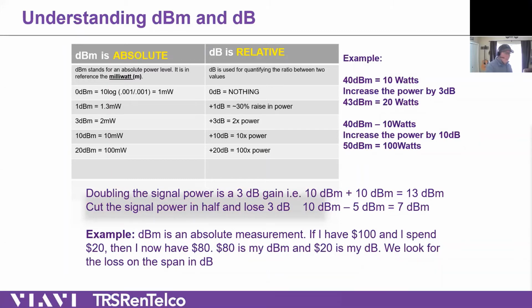And that number is good because obviously you need to know what that number is at the end, but you're not going to know how well your network affected that number. Hence the dB, or the relative value, right? So a decibel value is not absolute. It's based on a known power source, like an OTDR, or a source, like a CW carrier tone source, and a unit on the other side that knows the output power. Or in an OTDR's case, it does the same thing with one box, right?